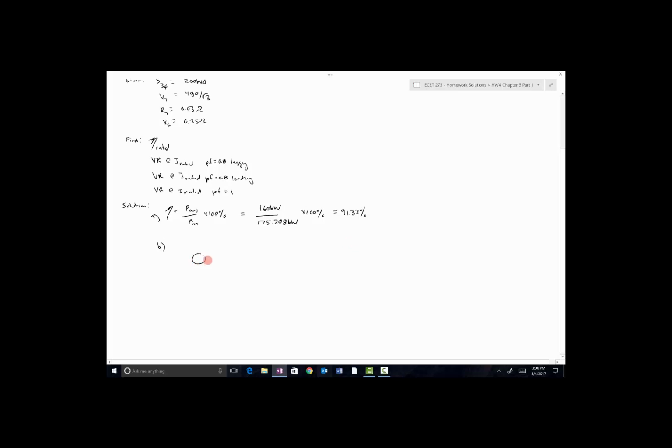I'll use the system model, the electrical model of the system, to explain that concept again. You've got the generator configured to provide VT under certain loading conditions, and by that, I mean there's going to be a voltage drop here, so you have to set EF appropriately to get rated voltage depending on what your load current is.